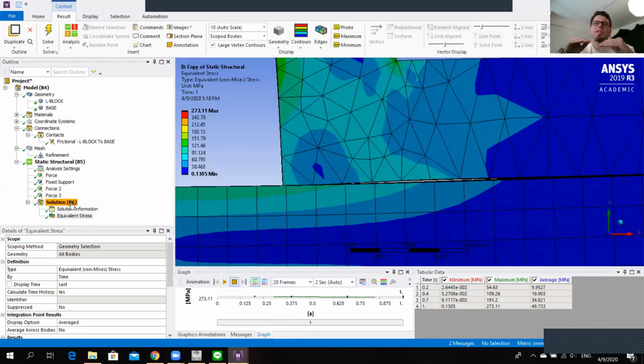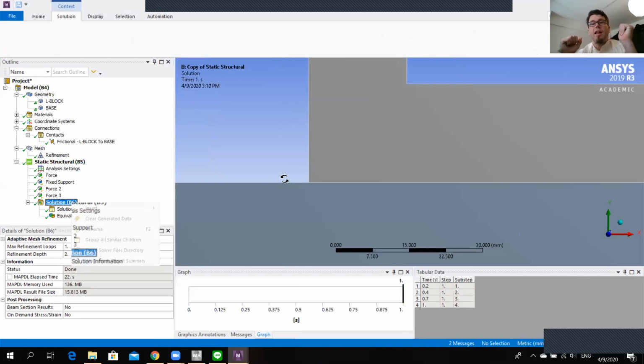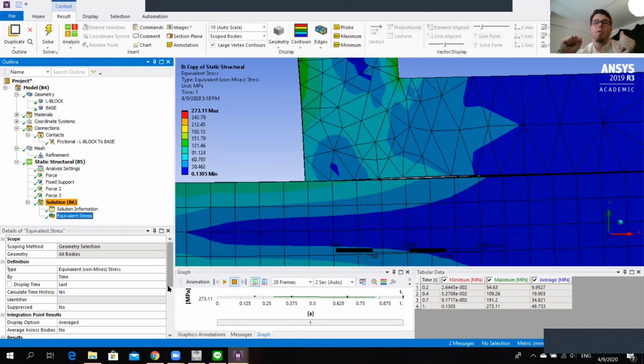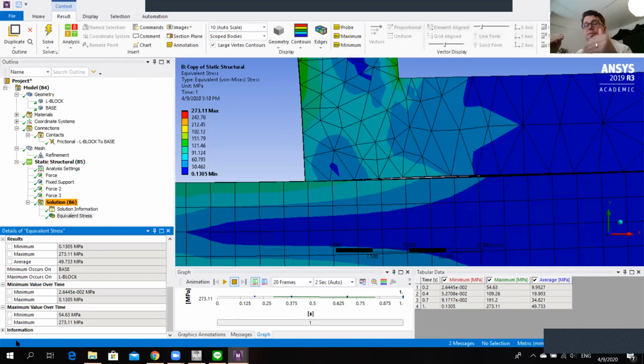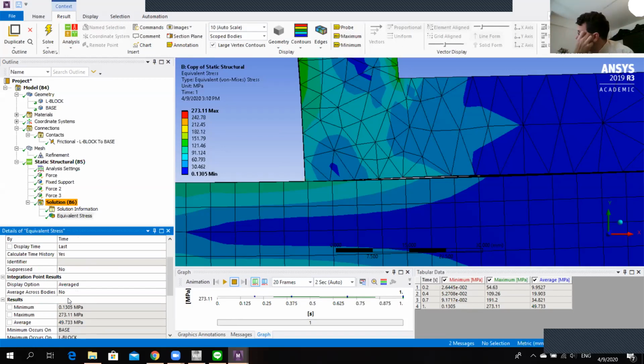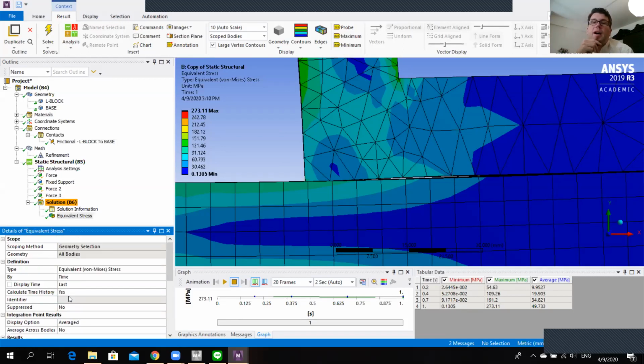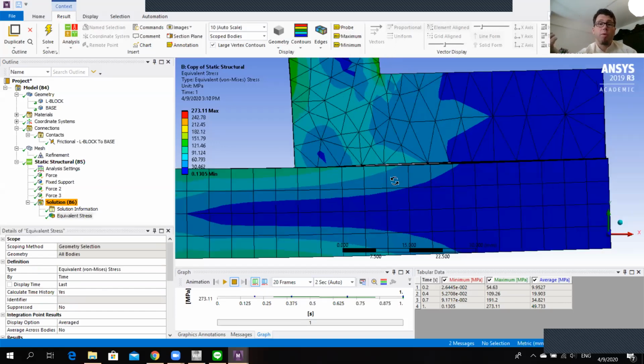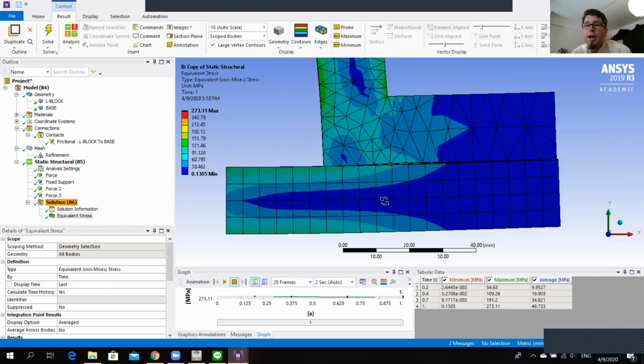Pretty beautiful. You can see how the L is leaning onto the steel part with the rear edge and lifting up in the middle, and that probably means that the screw would be stretched. Obviously, now there's the external force. It will result in an extra force acting on the screw, stretching the screw a bit more. But we don't know about this. We don't have the screw in the model.